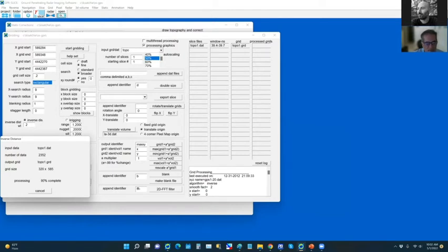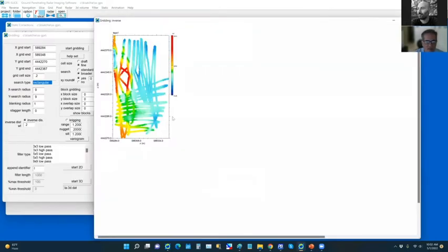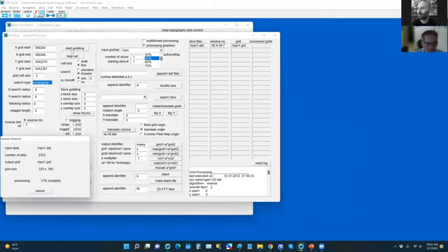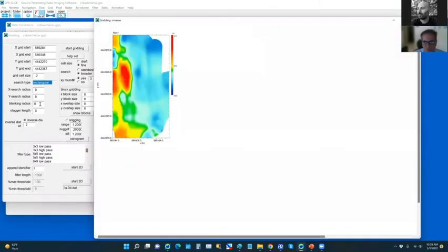And that's almost finished. And that's showing the track of the GPS. Well, we wouldn't want to create that digital elevation model. So we need to really fill that all in. So I'm just going to put in a larger blanking radius and let this run one more time. And just to note, the topographic grid has to encompass all of the data grid as well. So usually the blanking radius should be slightly larger than the blanking radius you used for creating the 3D volume.